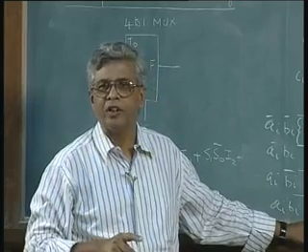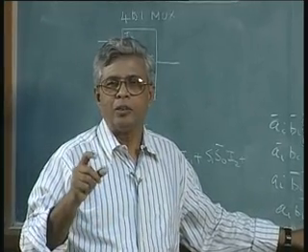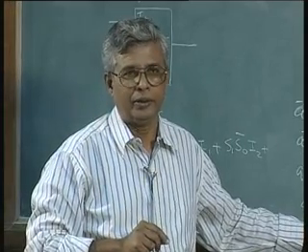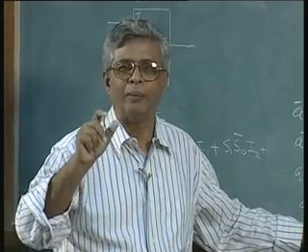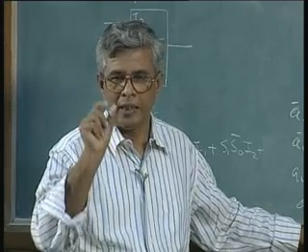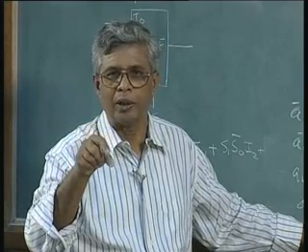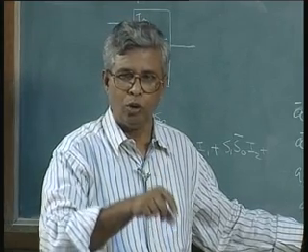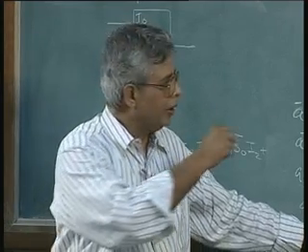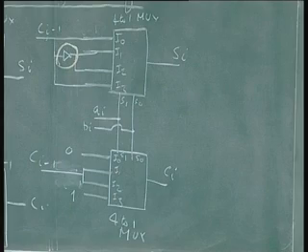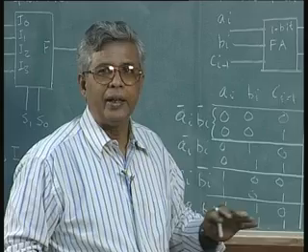The other significant feature of this design is that normally these multiplexers come in dual packages. You can't buy a single 4 to 1 multiplexer in the market. You have to buy it as a twin package. So, in one chip IC, you will get 2 of those 4 to 1 multiplexers. Since you are going to buy a package of 2 4 to 1 multiplexers, you can actually use both of them and get the entire design rather than buying 2 different ICs. That is another significant feature of this. This tells you how to proceed with available components.